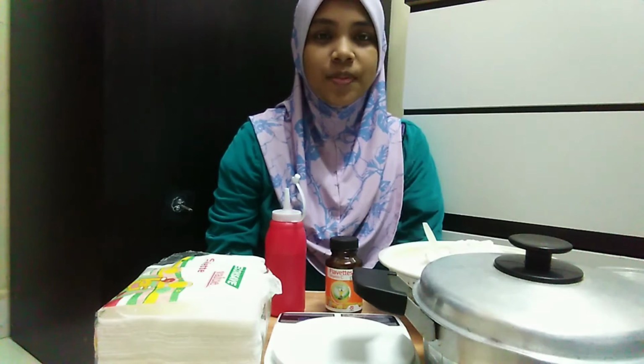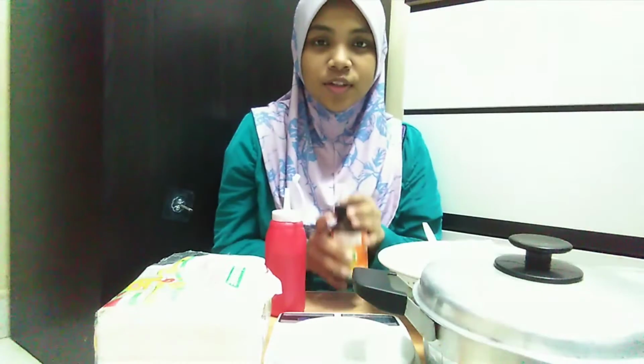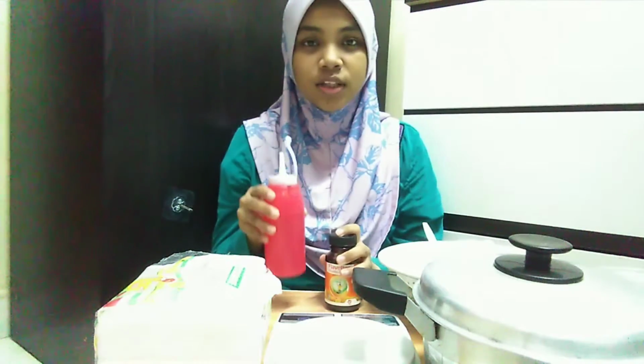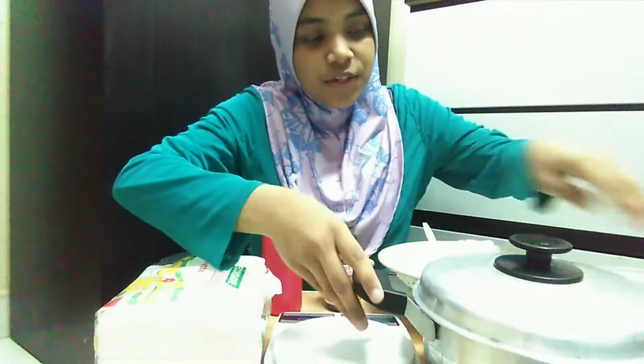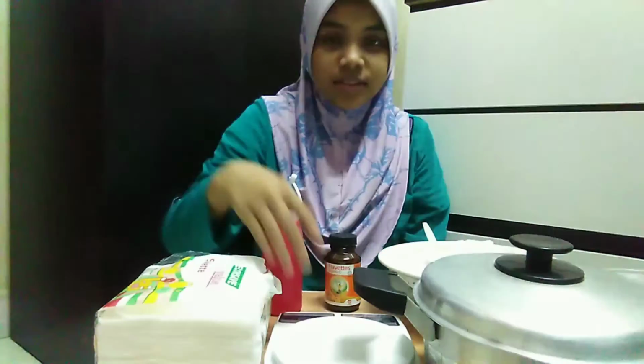There are three different tests for the particle density measurement. The first one is the density bottle method for fine-grained soil. Next, the gas jar method for soil that contains gravel-sized particles. And the last one is the pycnometer method for medium and coarse-grained soil. For the particle density test, we need soil sample, density bottle and stopper, distilled water, vacuum, water bath, and balance.